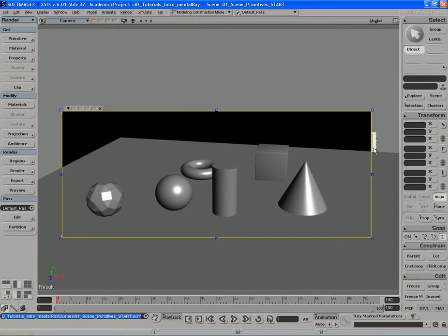Now if we lower the slider all the way down, our quality is going to be at the worst. But if you noticed, it rendered much faster, almost instantly. If you put it around the middle, you get a pretty decent balance of the two. Some better quality, not the best, but you get pretty fast render speed. So it's a trade-off that you have to accept. If you want high quality, you lose speed. If you want speed, you lose quality. So keep that in mind. I'm going to go ahead and keep it right in the middle so I get a good balance of the two.